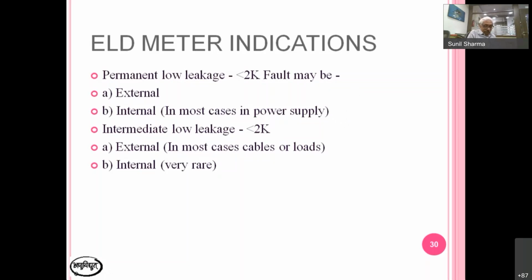If you have a generator, please put on the generator, and the charger should be run with the generator. Then disconnect your battery, both plus and minus. In most cases, we have found it improved. We take all these steps very carefully and with respect to safety measures. We have just established whether it is in the power supply or not. Suppose we have found that it is in the battery bank.